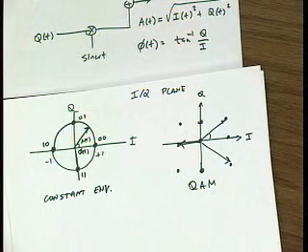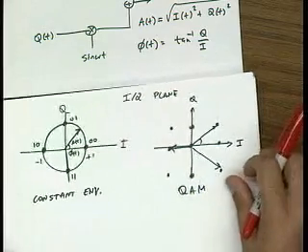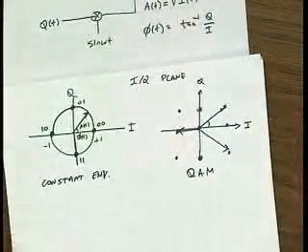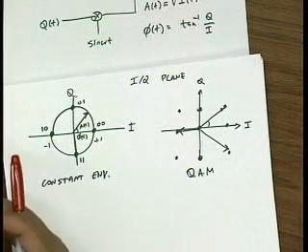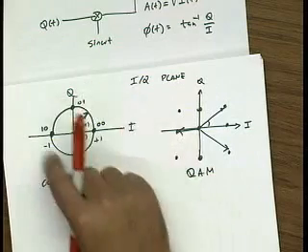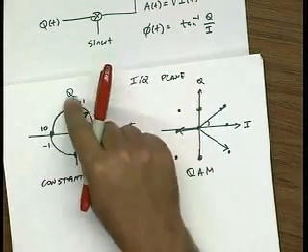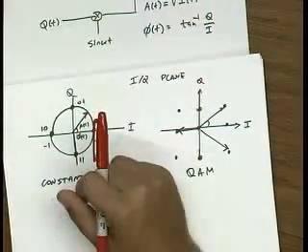Now, I won't go into detail about modulation schemes and their performance, but let us just say that the performance of a modulation scheme, the probability that you make an error, is also very much related to signal-noise ratio. And we talked about this briefly before, because if I transmit bits on this, what we call this constellation, what we receive are not actually these points exactly, because there's going to be noise in the system.